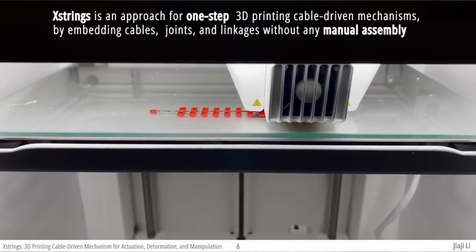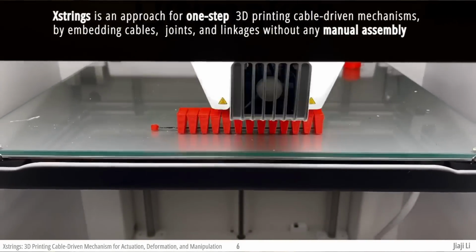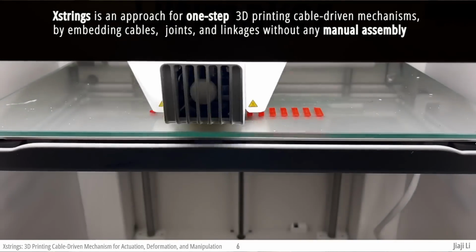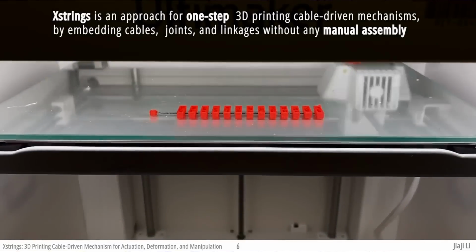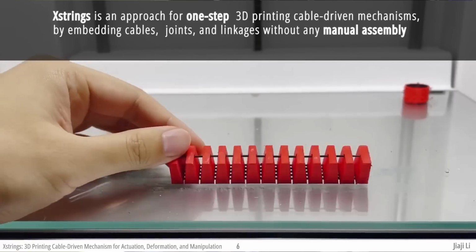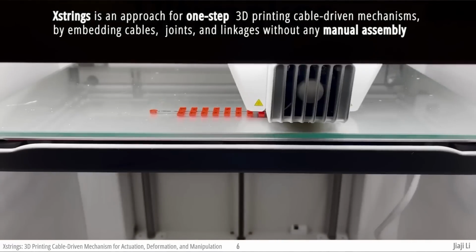To address these challenges, we present Xstrings, a method that enables 3D printing cable-driven mechanisms for one-step fabrication. This method prints cables using nylon material while controlling the G-code to prevent adhesion with PLA. As a result, no assembly is required. The moment it comes off the printer, it's ready to transform.